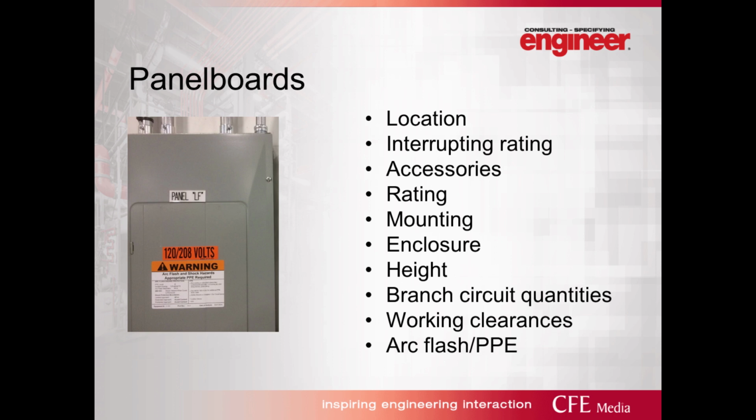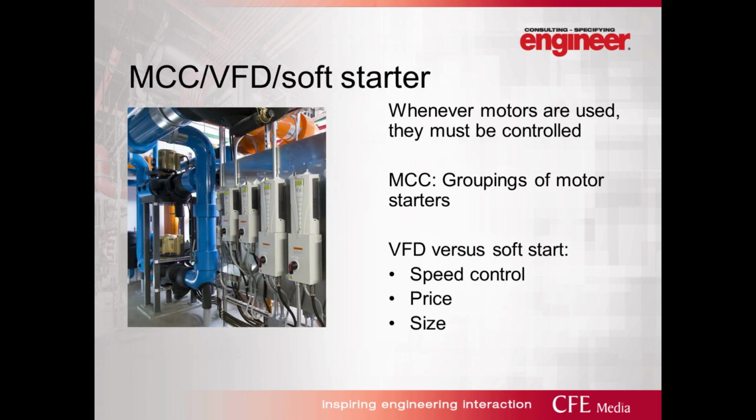The advantage is that the equipment costs are lower, but the disadvantage is that you have to calculate the available fault current at each device's location in the system. Healthcare facilities typically require a fully rated system. There is a maximum requirement for panel board mounting height. Per NFPA 70 section 404.8, the maximum breaker mounting height shall not exceed 6 foot 7 inches. Arc flash labels are required per NFPA 70E and OSHA.